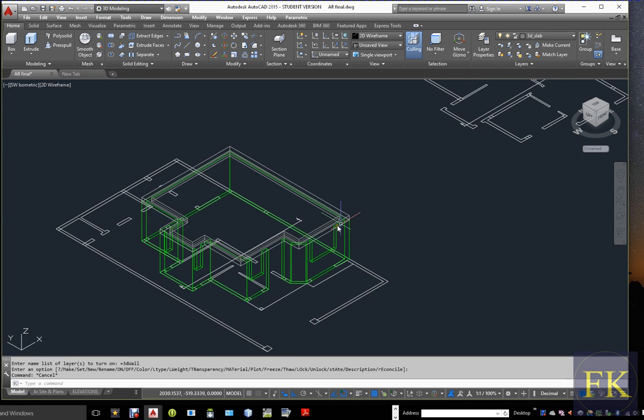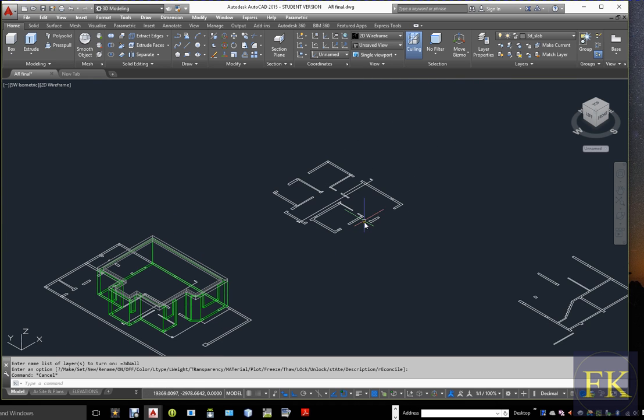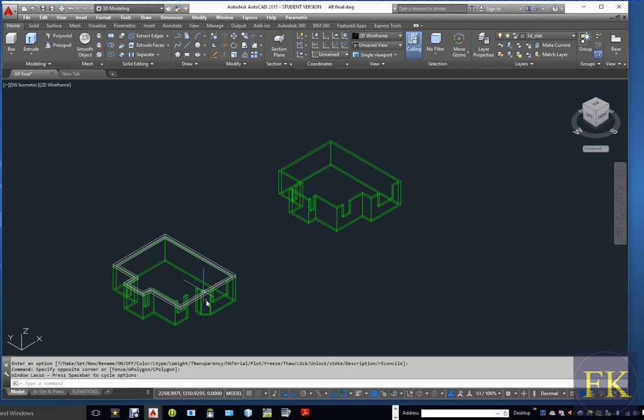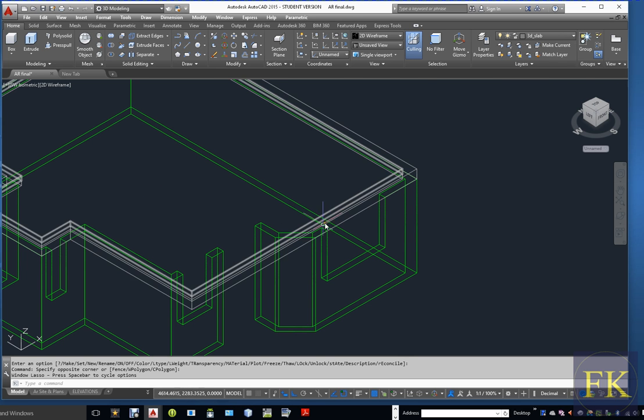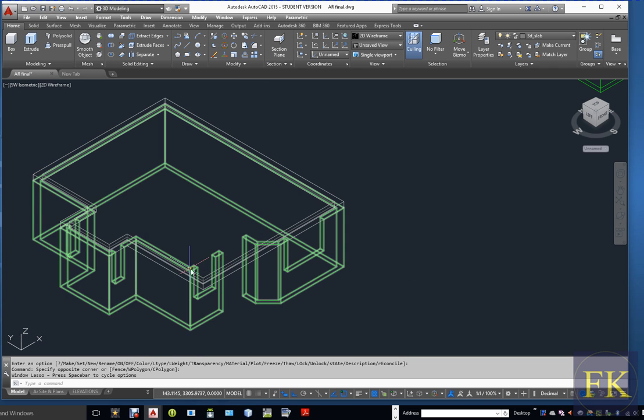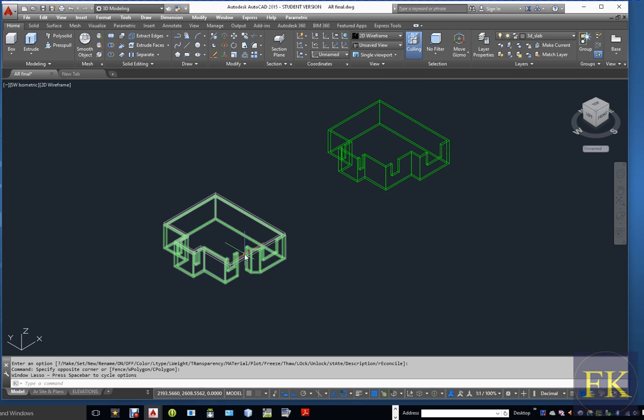And then I'm gonna turn off the video, and I'm gonna create the three-dimensional view of the top floor in the same pattern. It's just redundancy, so I'm gonna create this one and I'll be back. Okay, I just completed the first floor, pretty much similar to the ground floor. I just used wall command, and then I created a cutout for the windows, and then I just made a little modification on the beam that we created. Earlier we did it on this wall, but I needed just a little bit cantilever type slab, so I just pushed it a little forward.